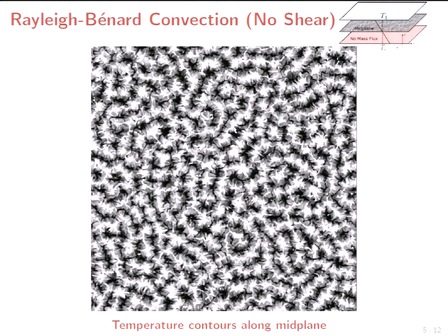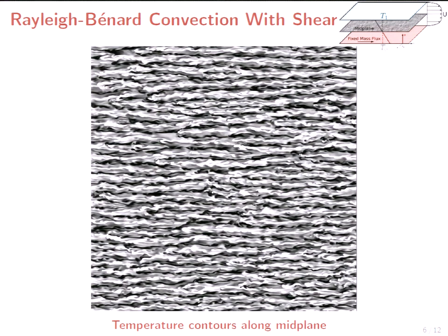And so this is just showing an example of what the flow looks like when you have just a vertical body force, in this case gravity, the acceleration of gravity, but with no mean shear flow. So you have these characteristic wavelength rolls, but these rolls are disorganized in this kind of spoke pattern, convection pattern. Now, if you were to apply a mean flow in this direction, so that you now have a mean shear in this flow, those originally disorganized roll patterns align themselves with the mean flow, and so this has consequences for being able to sustain the mixing and heat transfer in these flows.